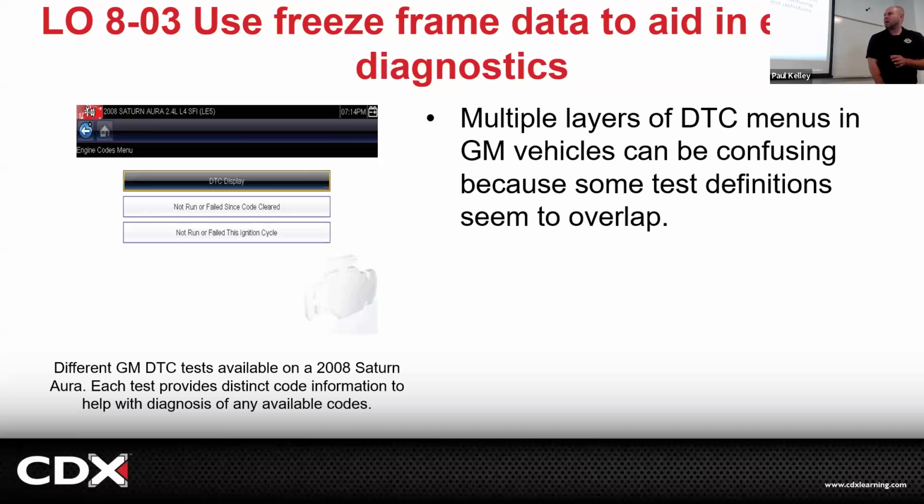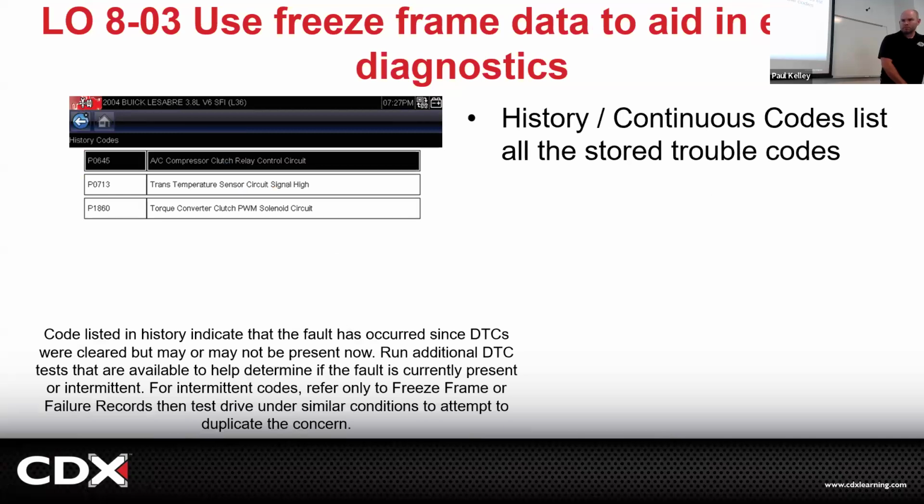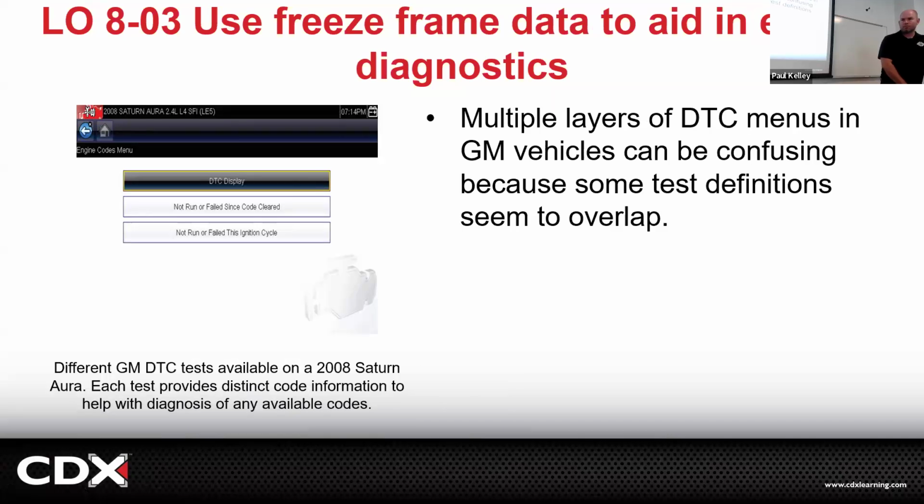Now, once you go in there and P0128 is not on the list of codes that have not run, that means it ran. And if the code didn't reset, that means it passed. That's a way to verify that the test actually ran and passed. You didn't think the onboard diagnostic system would be this complex. So if it didn't pass, it would set an active code. It would show, boom, no matter how long ago it happened.